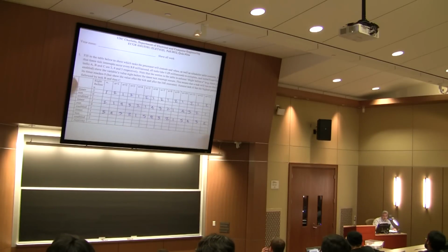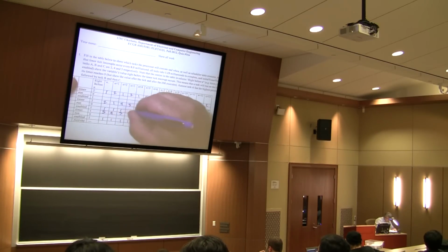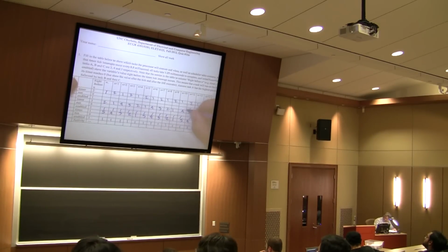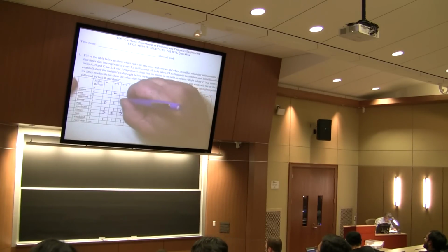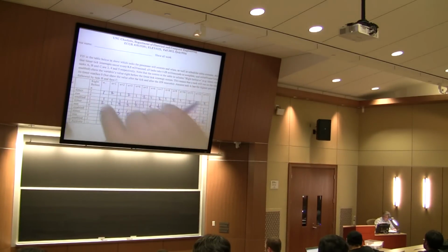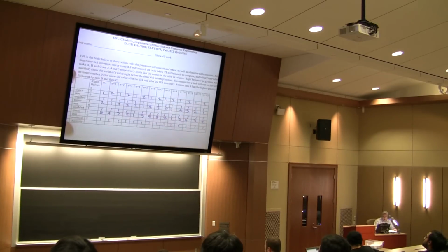It's always enabled. I don't say I'm ever disabling anything, do I? So these will all be 1. Boy, that's kind of easy, isn't it? And here's the other last easy assessment to make. Anytime I go from 1 to 0 and then it gets reset, I always set the run bit, right?